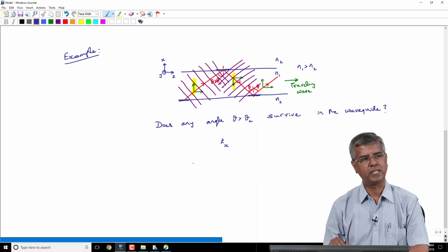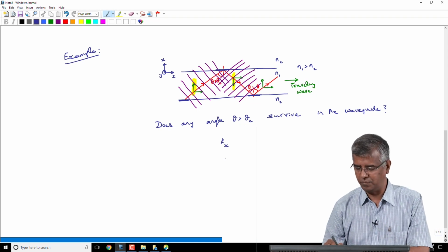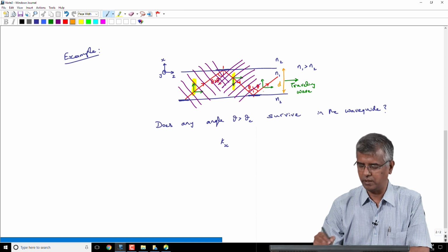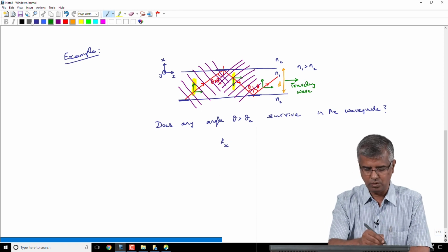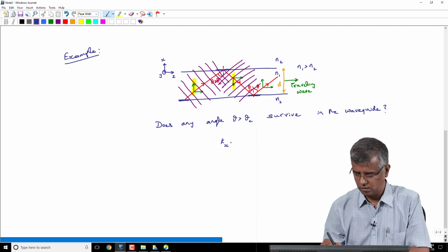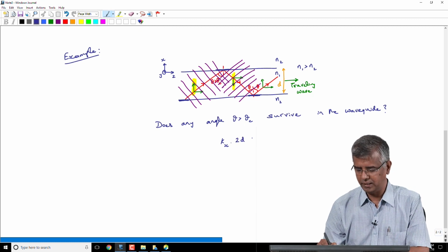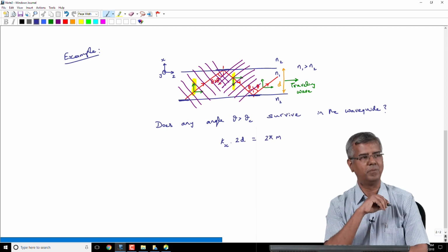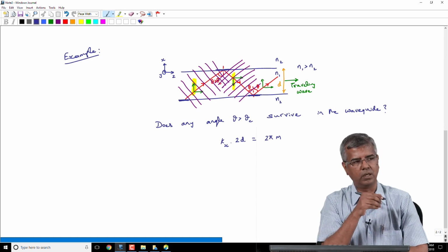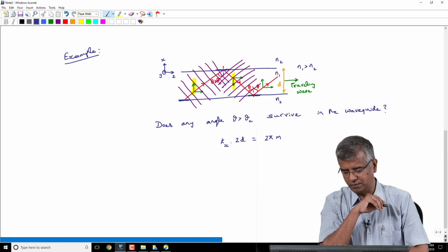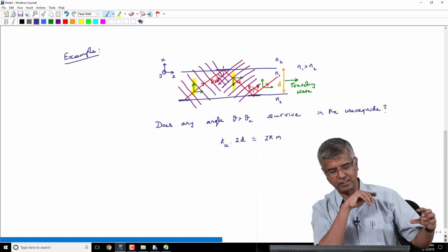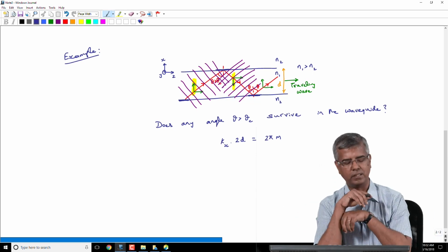So, I can write this as, if I say kx corresponds to the wave component in the vertical direction, and let us say this waveguide has got a dimension d. So, kx multiplied by 2d has to be integral multiples of 2 pi. So, that has to go through the constructive interference criteria. So, essentially the same field configuration is consistent as this wave is going across.